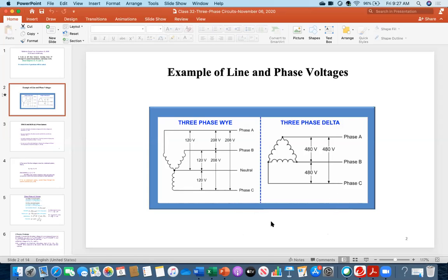That is one thing. The other problem can be, this is the neutral line. You might have noticed outside the overhead line, the telecommunication line or the telephone line, they carry the same neutral line. So therefore, for example, your system is unbalanced and current is flowing. The same current is flowing through the neutral of the telecommunication line.